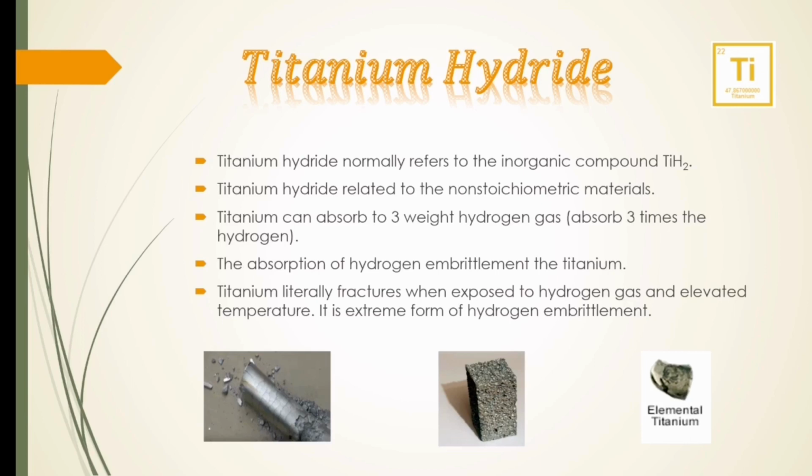So next we are going to move on to titanium hydride. Titanium hydride normally refers to the inorganic compound TiH2. The titanium hydride is related to the non-stoichiometric materials. It can absorb 3 weight percent hydrogen gas, and the absorption of hydrogen embrittles the titanium, which means the titanium is getting brittle when exposed to hydrogen. So the titanium literally fractures when exposed to hydrogen gas at elevated temperature. It is an extreme form of hydrogen embrittlement.